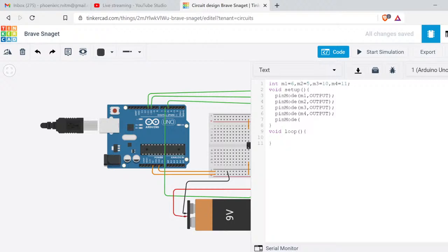First, I have to declare LIR, signifying the left IR sensor, which will be connected to the second pin, and the right IR sensor will be connected to the third pin. I am not showing it in connections. I just showed the connections of that, and as the IR sensor is not available, I just explained by code.